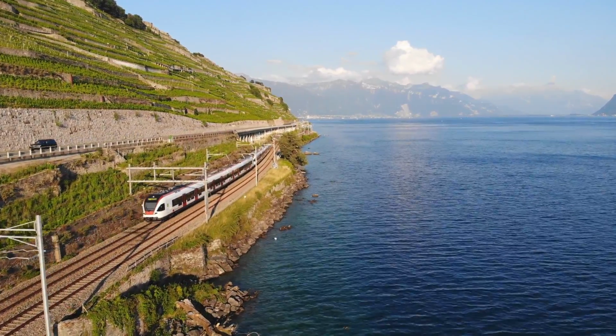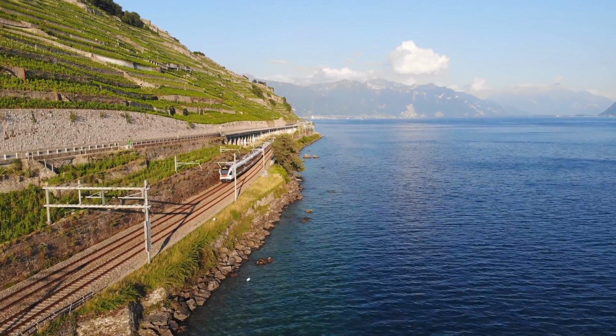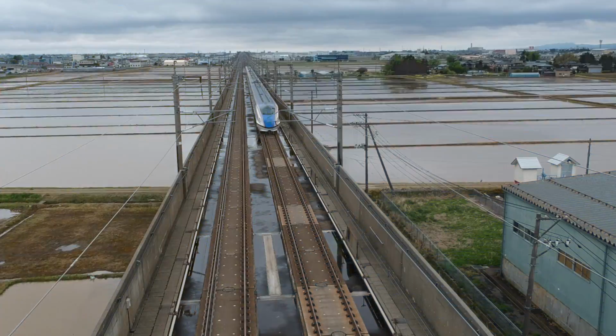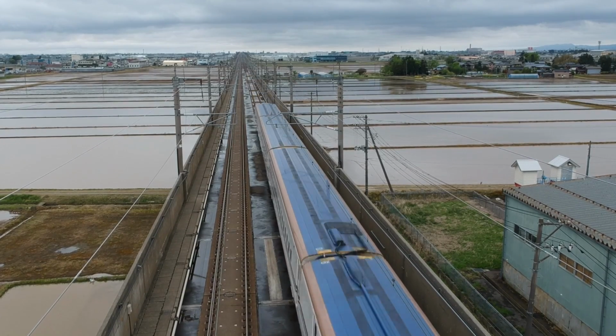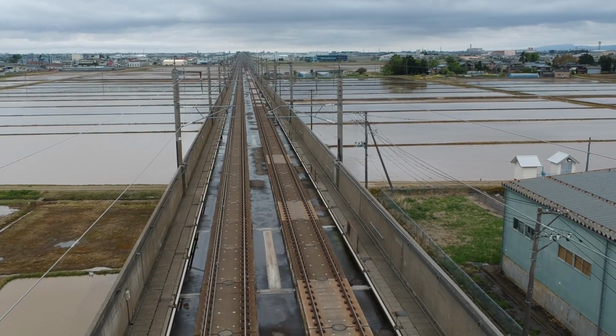So, in summary, slab track has significant advantages over conventional ballasted track that makes it suitable for some applications such as high-speed lines or where high levels of track fixity is required. It also has lower maintenance costs. However, this does come with a bigger price tag for the initial installation and lower flexibility once it's installed.